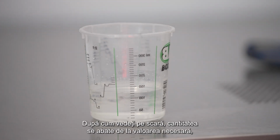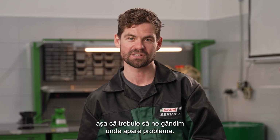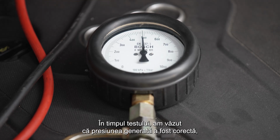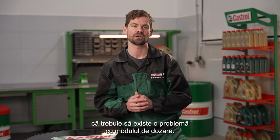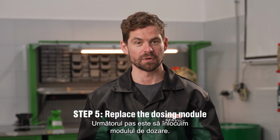As you can see on the scale, the amount of fluid deviates from the required value, so we need to consider where the problem occurs. During the test, we've seen that the pressure generated was correct, so we can logically conclude that there has to be an issue with the dosing module. So our next step is to replace the dosing module.